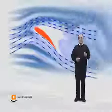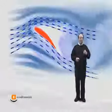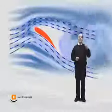Just to summarize, when we increase the angle of attack until the critical value, the flow separates on the upper surface and the drag increases a lot, while the lift abruptly decreases.